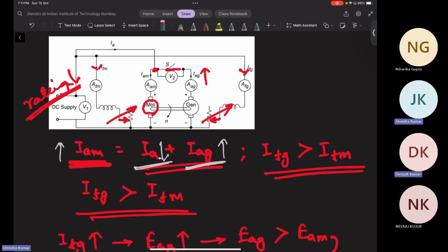But whenever, what's the field current of the motor? Will it be the same now? Whatever the field current, you can vary the field current because it is connected in parallel to that, right? But this IA will depend on the rating of the machine. VT into IA, right? Of a DC machine. VT into IL, and IL is nothing but IF plus IA. VT into IL is the rating of the machine, right?